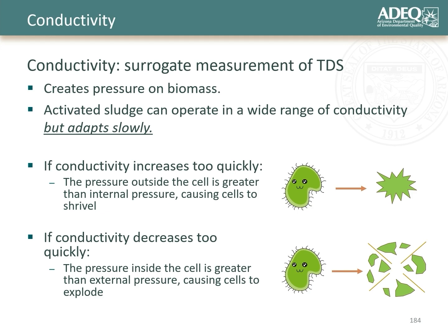So as we start looking at groundwater that is higher in total dissolved solids over time, which then becomes wastewater that has higher total dissolved solids concentration, or as the case may be with potential direct potable reuse in the future, where maybe total dissolved solids will build up as part of that, all of this could change your TDS and your conductivity of your wastewater. Just something to think about in terms of the performance of your system.